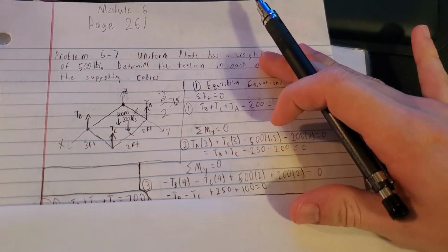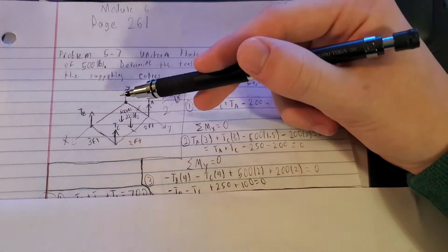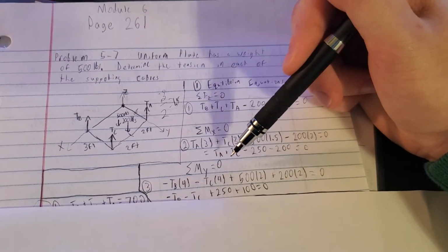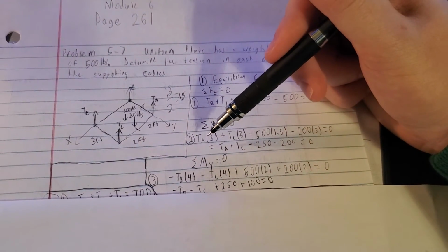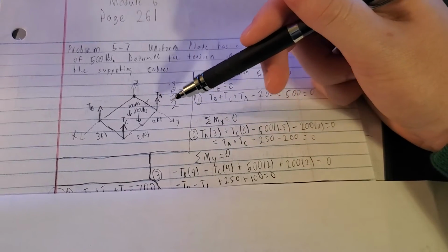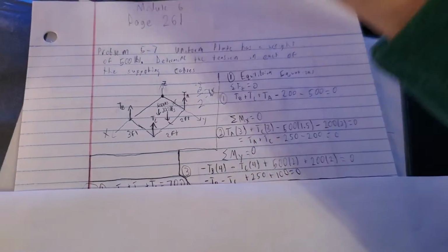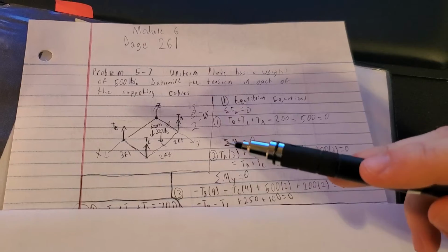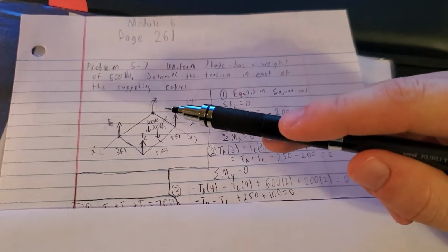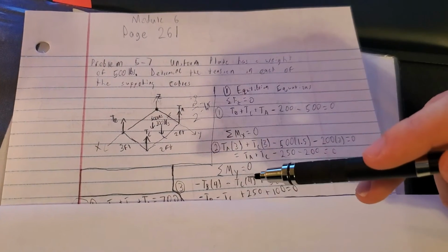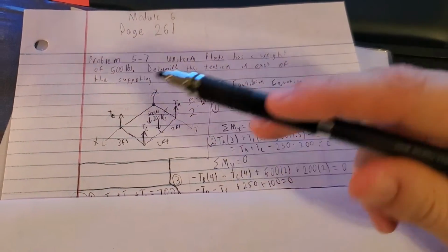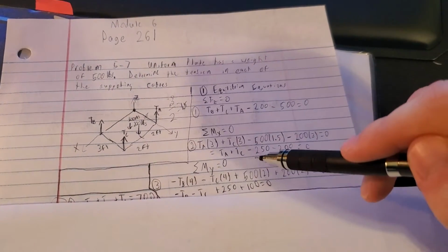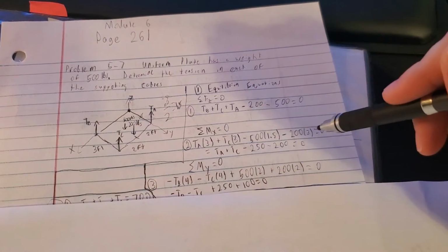And then you solve for your moment about the Y acting from this spot. Okay, I'll explain why these are positive over here. TA times 3. So this would be going around in a counterclockwise motion from the point at the origin. So it would be counterclockwise, so it would be positive. And it's the same with the TC. This would be going counterclockwise, and since these are going down, they would be going clockwise. So they're minus. This is clockwise, and this is clockwise.